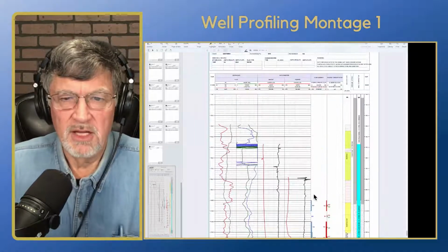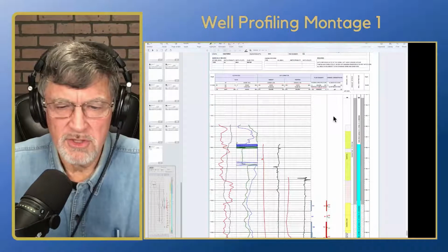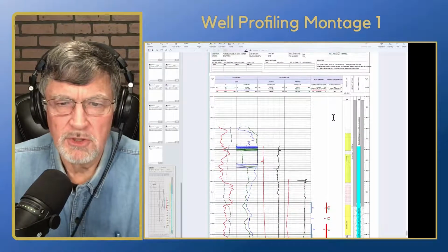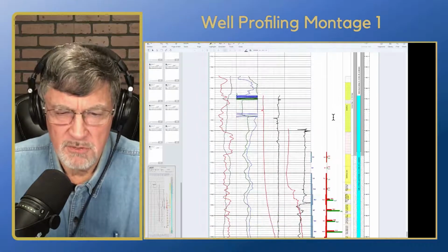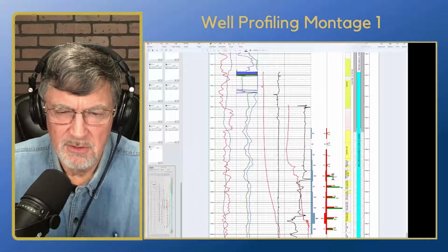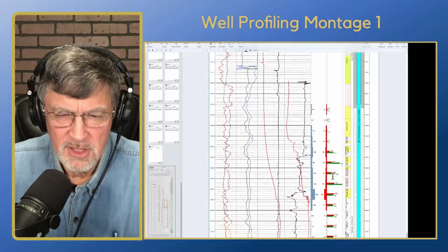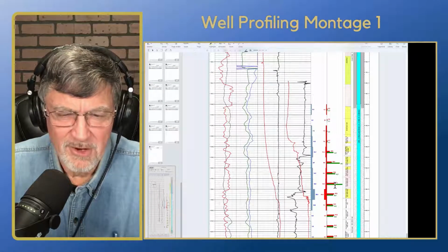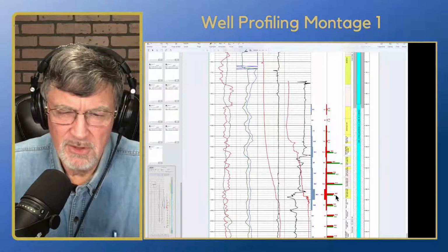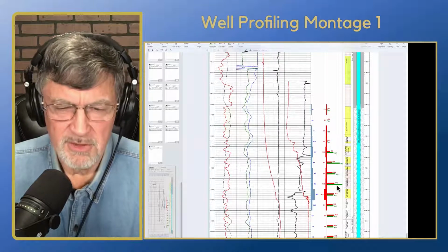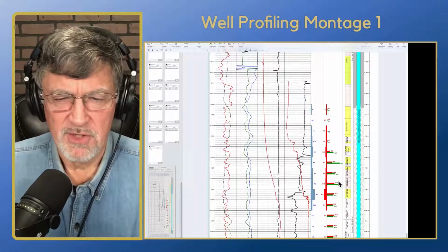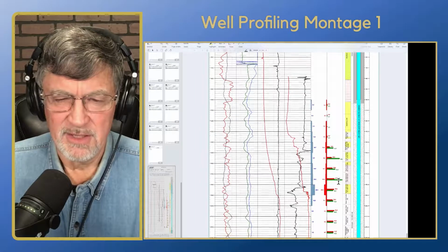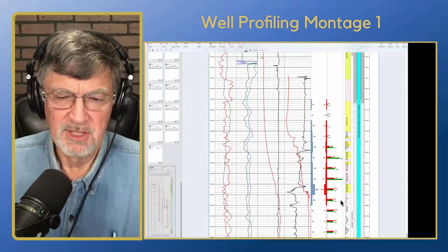So, and then we look at here is our arsenic concentrations observed and estimated. Observed is the red, and estimated is in the green. So we can see we have our highest arsenic is right above this zone. We could have fiddled around here a little bit with the well screens, but the operator decided to take it all and do some blending as treatment.